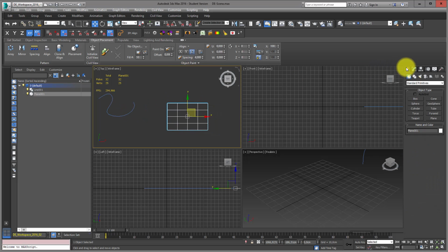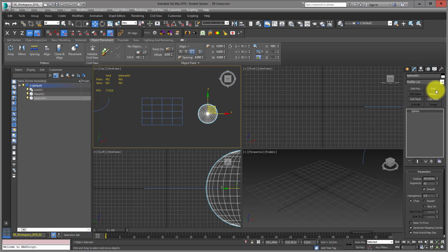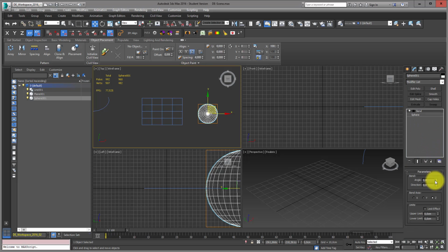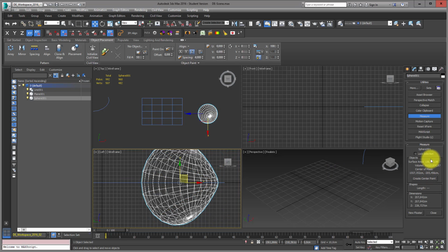And if I draw an object, for example like this sphere, and of course you can also put modifiers on top, and I just bend this right now to make it a little bit different to a sphere. You can again go into Measure, and here you can see the surface area and the volume, and this is also a function you can use if you need it.